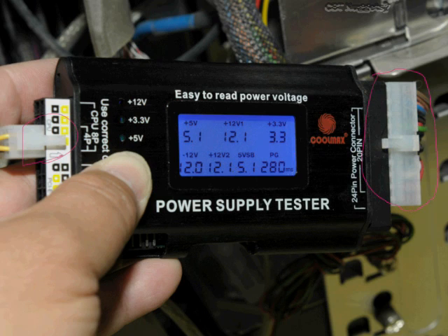I have to push that on, and the reason is that normally the power supply does not come on unless it gets a power OK signal from the motherboard, because there's a switch. You know, on the front of your computer, there's a switch that's connected to a block on the motherboard. Well, with this being disconnected from the motherboard, there's no way for it to communicate with that. So I have to push down the button in order to turn on the power supply.